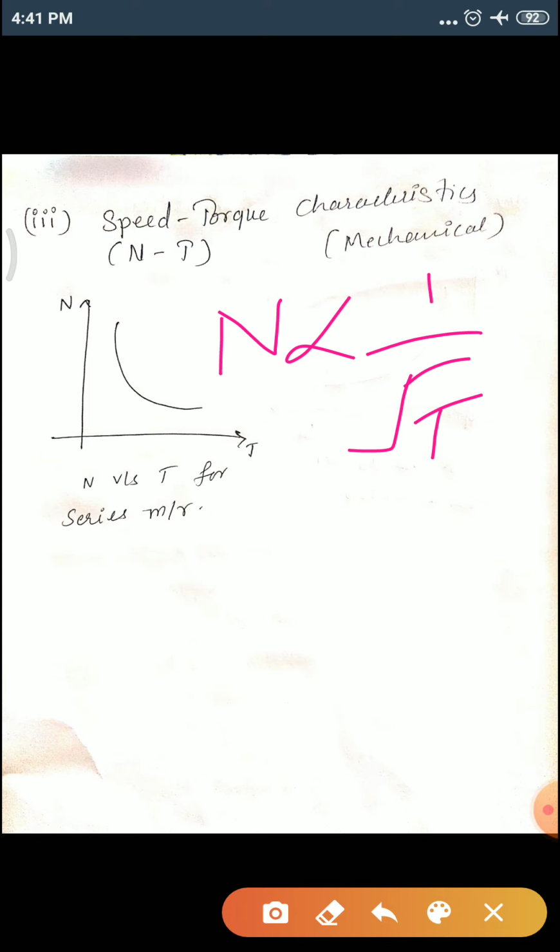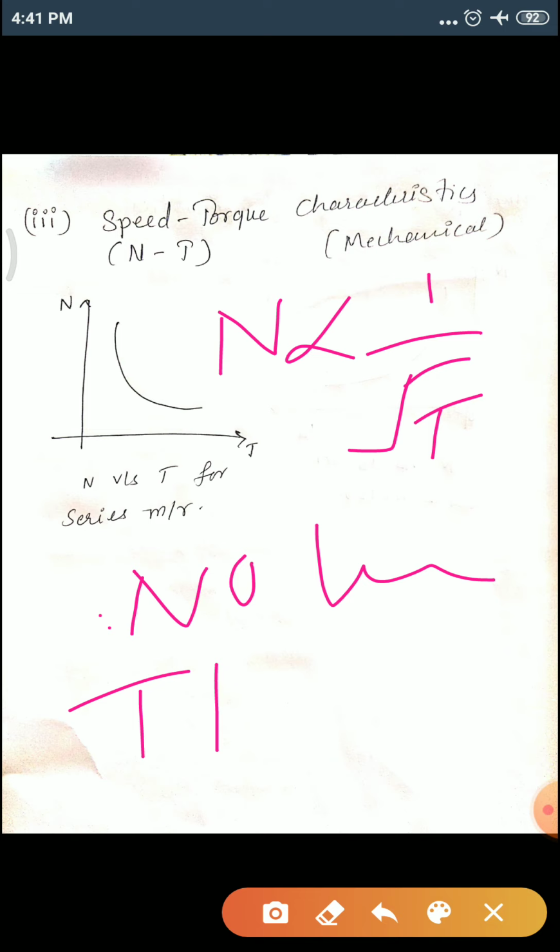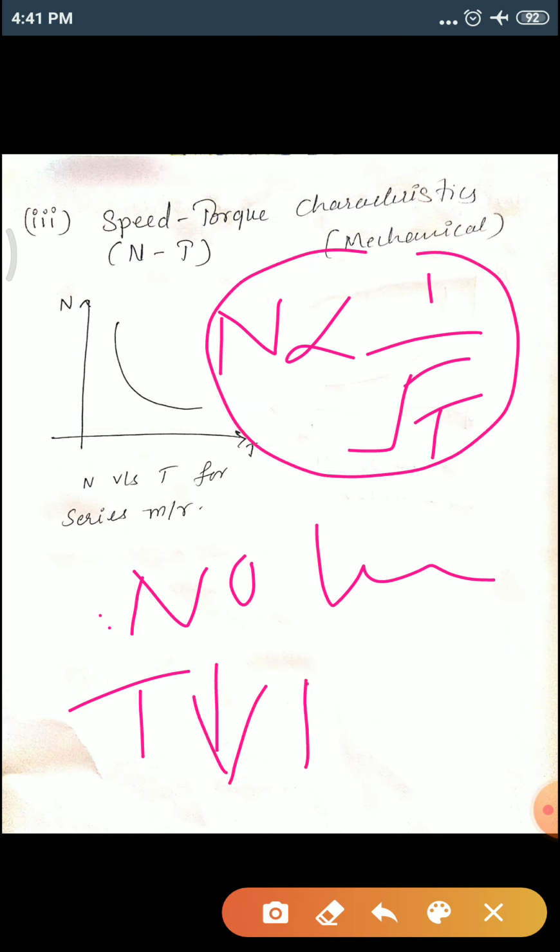The torque increases when you put a load on the motor, so what happens is torque increases, and the speed goes on decreasing. And then when on no load, torque is very less. And then what about this formula? N is, and hence the speed of the machine will increase to a very dangerous value, means very dangerously it is going to increase its speed.